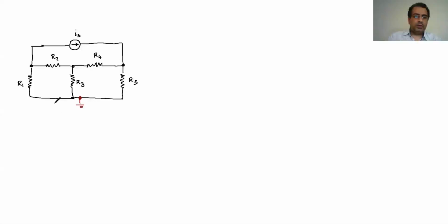So I choose this node down here as a reference. It's the starting point. After that, I know that this node is going to be negative, and every other node I have is going to be positive compared to this one. Then I would consider the voltage at each of them. So this one I would call V1, I name these two V2, and name this one V3.